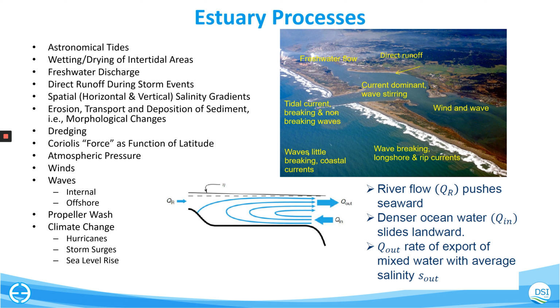Freshwater discharges, these are mostly going to be the same kind of setup that we looked at for Lake T, just simple time series. Direct runoff, you may be able to apply some simple engineering equations just using impervious area and rainfall intensity to compute these, or maybe you bring in a more advanced hydrologic model in order to make those predictions. Salinity gradients are a huge factor in a lot of estuaries. Often the intrusion of salinity into an estuary is a topic that we'll be concerned with in our modeling.